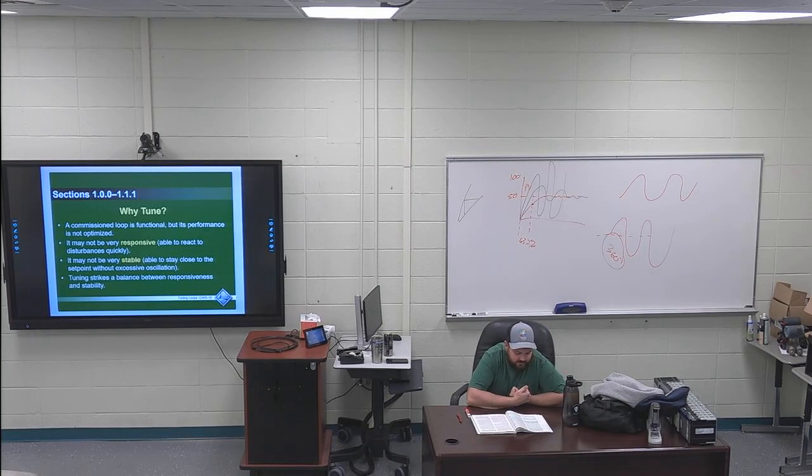Last paragraph in that section, I've got the whole thing highlighted for 2 questions. One question comes out of the first sentence and the other question comes out of the whole paragraph. But during controller tuning, the goal is to adjust the loop's gain so that it is less than 1 at the critical frequency. If this is done correctly, process oscillations will die out as quickly as possible and the controlled variable will remain near the set point. This section explores different ways this goal can be reached.